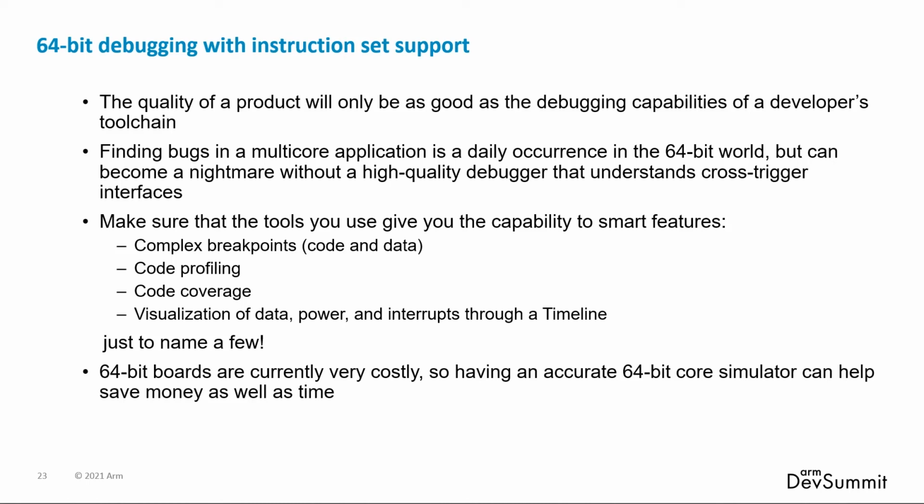is critical for debugging those complex synchronization issues. The days of writing code, running it, and seeing if it all just works are long gone with these kinds of complex systems. Also, having a software simulator available as part of your execution environment can be critical. This is true because 64-bit boards can be much more expensive than their 32-bit core brethren. But also, when building unit testing frameworks, you often will want to test code fragments in a pure software environment without tying up valuable hardware resources and debug probes.